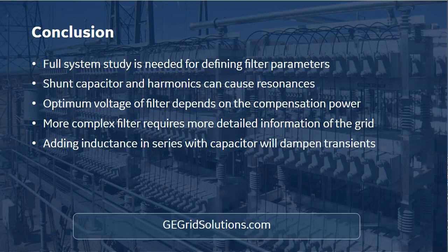Okay, then we have here a question about the filter design basics. So what is really the design basics? I would say that, as I told you earlier, first you determine the reactive power needed by filtering, filter types and quantity, what kind they are. Then determine the connection voltage based on availability and choices and the needed compensation power.